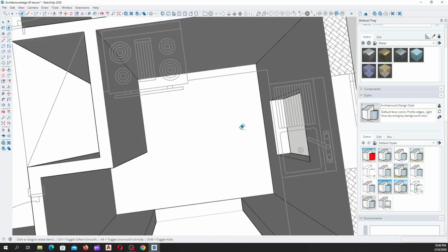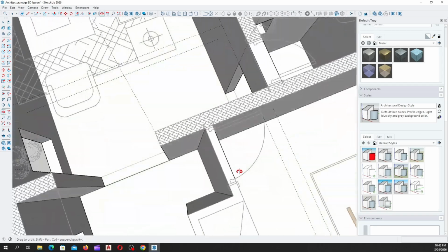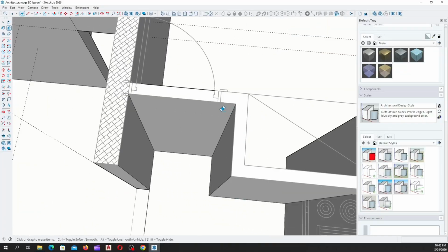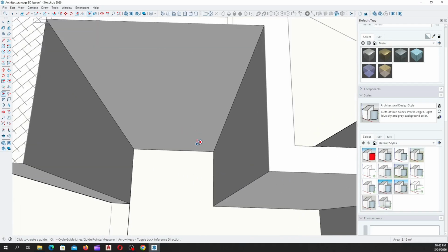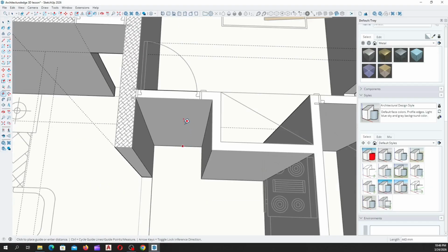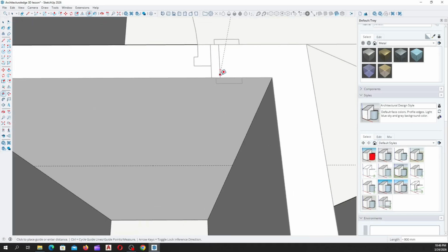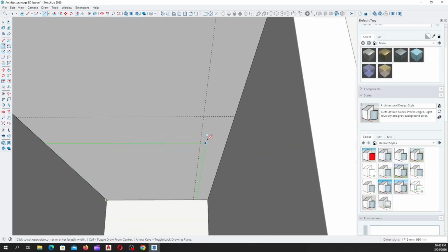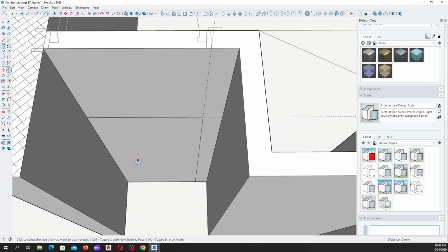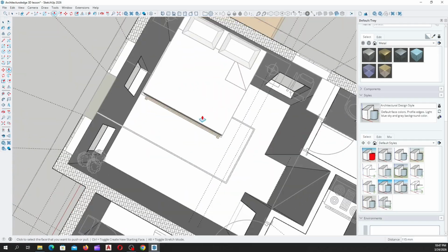So this portion here is our kitchen area. This is our living area, our living room. Then also from here we have our bedroom. All right, this is a little lobby to access our bedroom. So we'll pick our tape from our ground level. We'll offset the value 2100 for our lintel. Then we pick from this angle and snap it to this end, which is the width of our bedroom door. Then we'll pick our right angle tool and enclose the mapped out area. Then our push tool. Then we push inward. We have our door opening to access our bedroom.